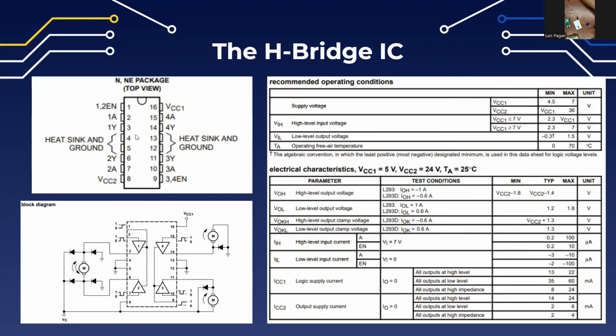Again, most of the power that you need for the motors is being provided by VCC2 and is separate from VCC1. You can just plug this into the same power lane connected to the Pi or breadboard. Just make sure that you don't apply too much voltage. Like here, the maximum is 7 volts. If you apply more than that, then you risk shorting something, and you do not want to do that.